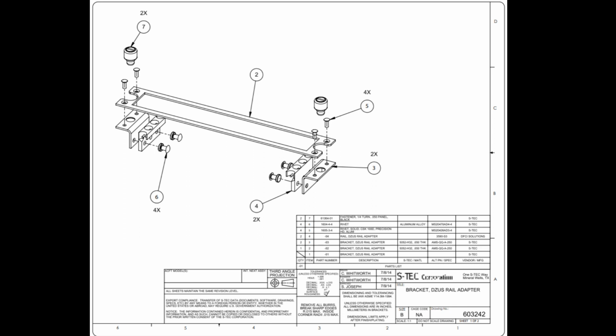2.01, 1.99. A print tolerance, usually found in the title block, is a general tolerance that can be applied to parts where the dimensions are non-critical. Where a tolerance is not shown on a dimension line, the print tolerance applies.